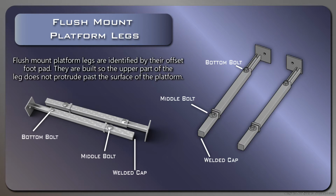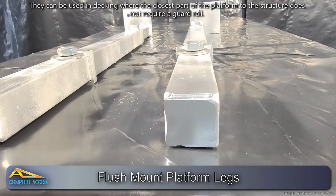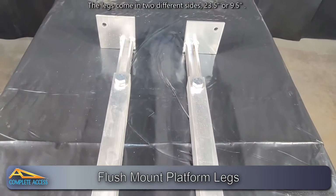Flush mount platform legs are identified by their offset foot pad. They are built so that the upper part of the leg does not protrude past the walking surface of the platform. They can be used in decking where the closest part of the platform to the structure does not require a guardrail. They come in 2 different sizes, 23.5 or 9.5 inches.